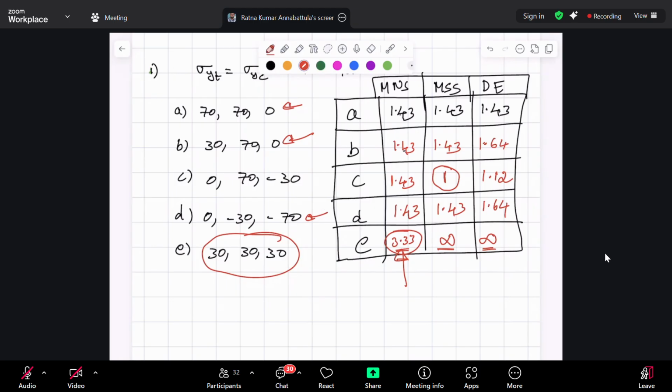Okay. The denominator is what? The denominator is the shear yield strength divided by the maximum shear stress, and here the maximum shear stress is 0. No matter what the numerator is, the denominator is 0. That is why it becomes infinity.